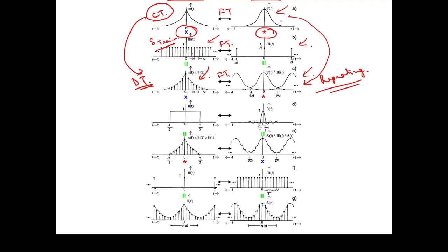Why? Because if you do not limit the band frequency component, say for example, 0 hertz to 100 hertz, then what will happen? When it is repeating itself, there would be overlapping. So say 0 to 100 would be there, and again some components which are repeating itself would overlap with the system.